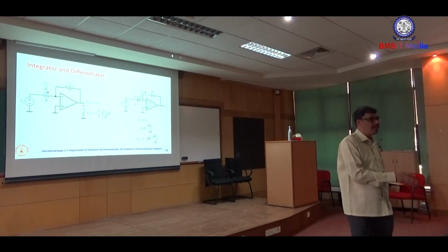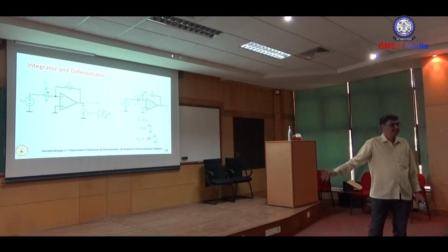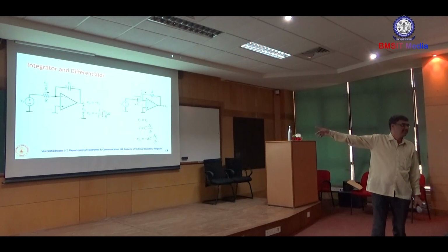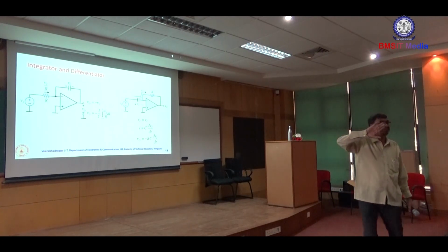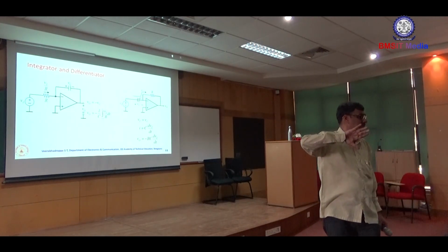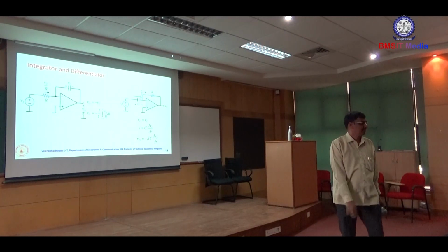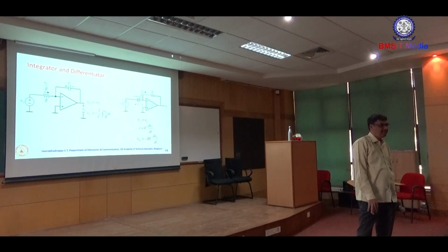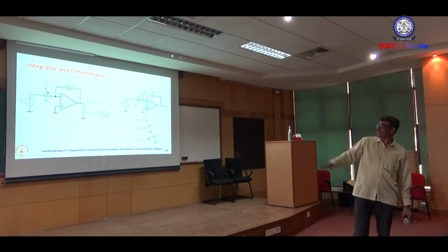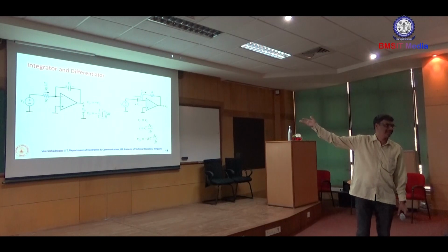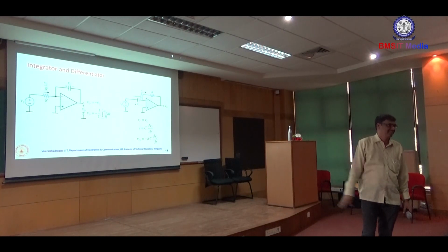Means whenever any sinusoidal signal is applied to any circuit, your output is sinusoidal only. But the only thing is, you can observe there is a phase shift or a phase difference because of that capacitor C. Have you heard about the non-sinusoidal signals? Can you tell me any name? Pulse, triangle. Okay, when you apply a triangle wave to the integrator, what is the output voltage? When you are applying a square wave, pulse, what is the output?